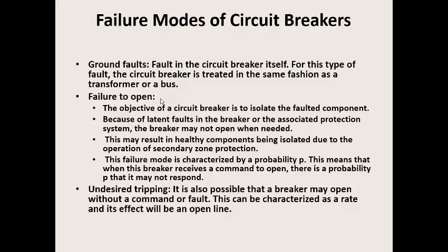But when the backup breakers open, then you will have a larger area which will be isolated than if the breakers open properly. So for that reason, the failures of the breakers not to open can lead to larger outages and also can lead to the cascading outages.